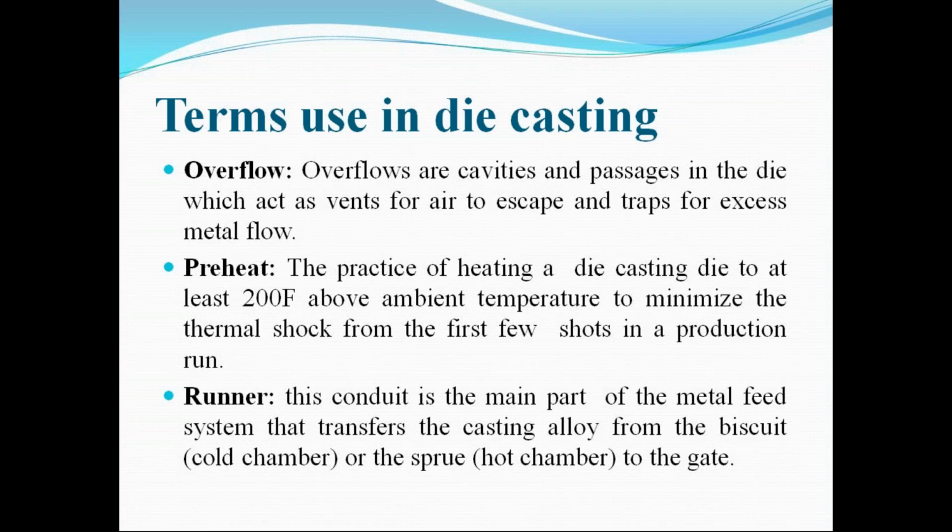This is not required for the product itself, but it is required for a quality product. So overflow is an excess volume of the liquid material which is not related to the product dimension. Overflows are cavities and passages in the die which act as vents for air to escape and traps for excess metal flow.